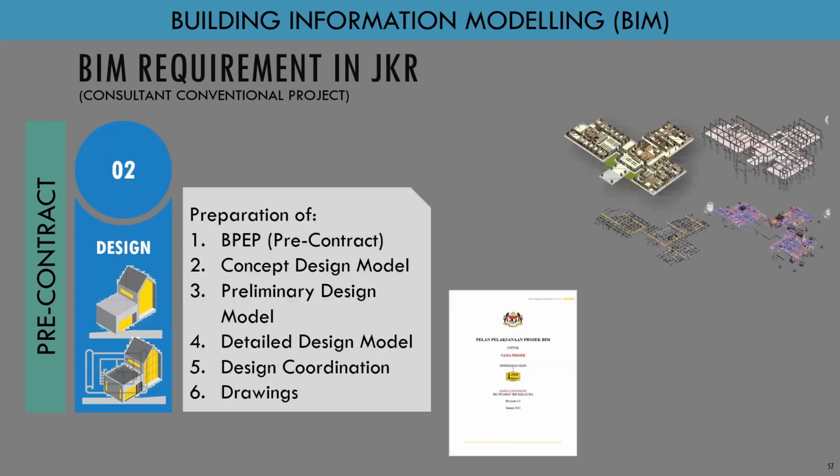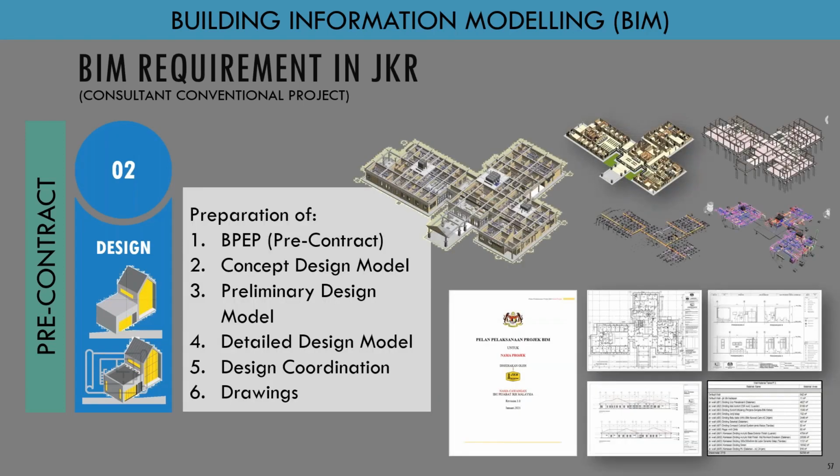Next, we go for the design. When the consultant is already appointed in JKR projects, this is the preparation they need to carry out. First of all, they need to do a BPP, the BIM Project Execution Plan. We have our template, so just use it. This one the architect will lead.